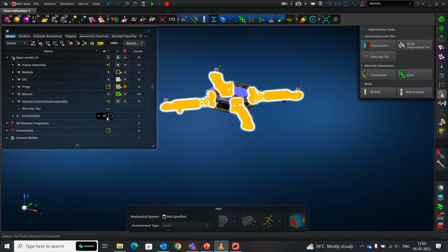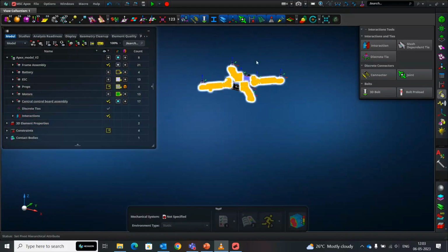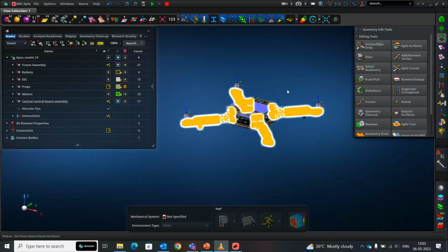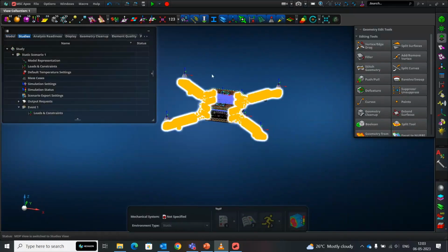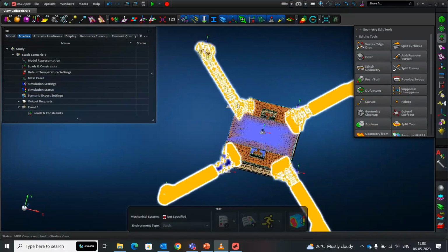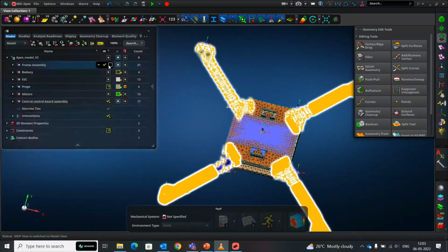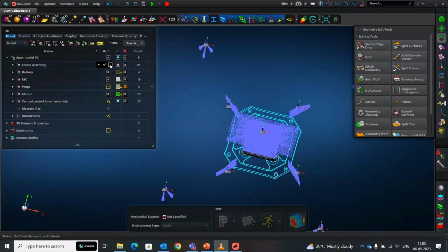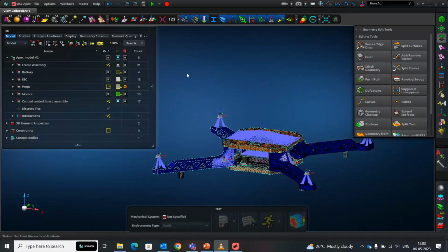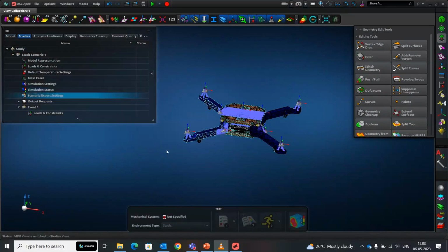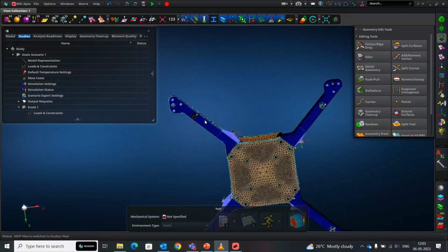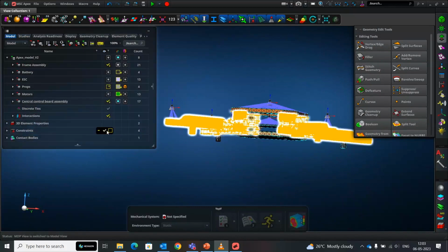So next, what is the next thing that we're going to do? So we have the mass, we have the boundary condition applied. We need to apply a loading condition. So a load condition becomes important to us. And here you can see how we go ahead and create a scenario. So we need to create a scenario. And basically what we do by creating a scenario is we go to studies and we have different kinds of scenarios that we can create.